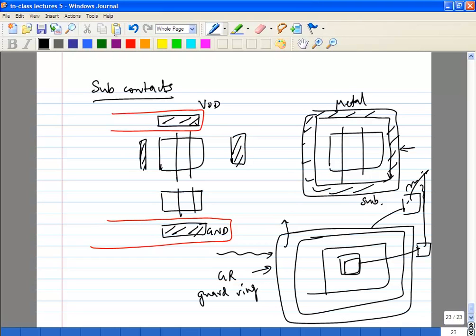Let us say it's coming here, and at this point the noise wants to split. You're going to have a very good connection to ground on the PCB, let's say. So it is going to prefer to go there instead of coming back through this. That is the idea. Try to increase the impedances on the two paths. That means apart from ground we should have two more, one for substrate, one for guard. Apart from normal ground. Okay, that will be your best choice.